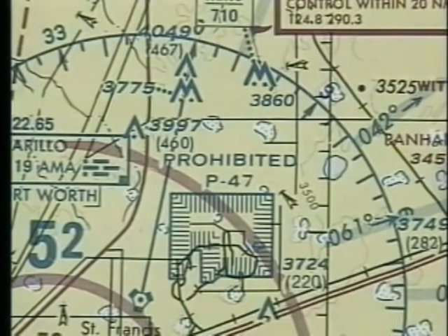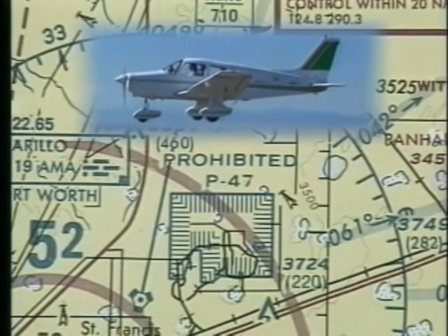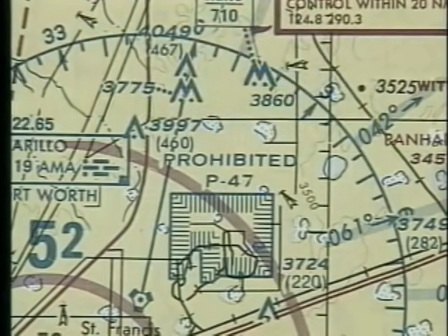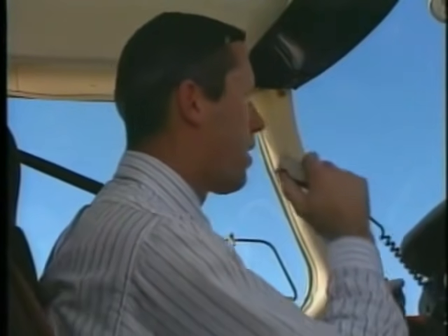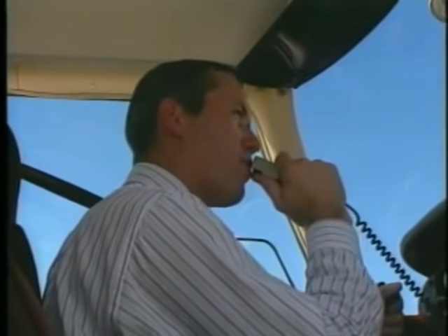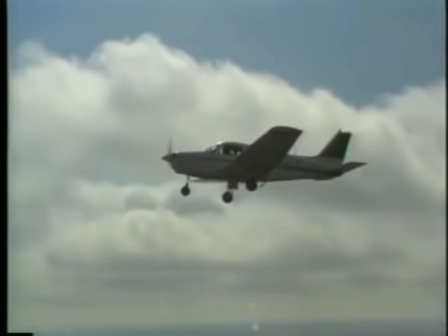Another major type of airspace is called special use. You may be required to avoid these areas or to abide by certain limitations within them. For example, flight within prohibited areas is not allowed because of national security or other reasons of national welfare. In contrast, flight within a restricted area is not prohibited, although certain limitations may be imposed due to hazards in the area. VFR flights must contact the controlling agency, while an IFR clearance through the area constitutes an authorization to penetrate the airspace.